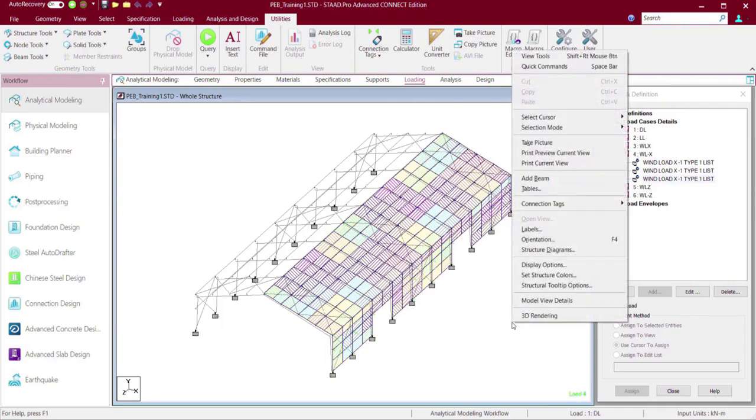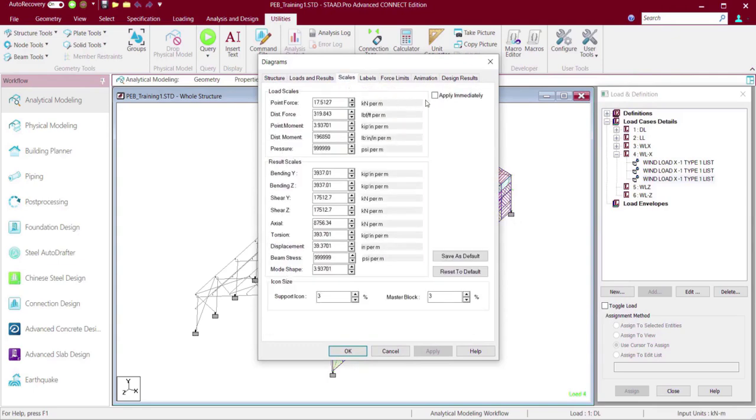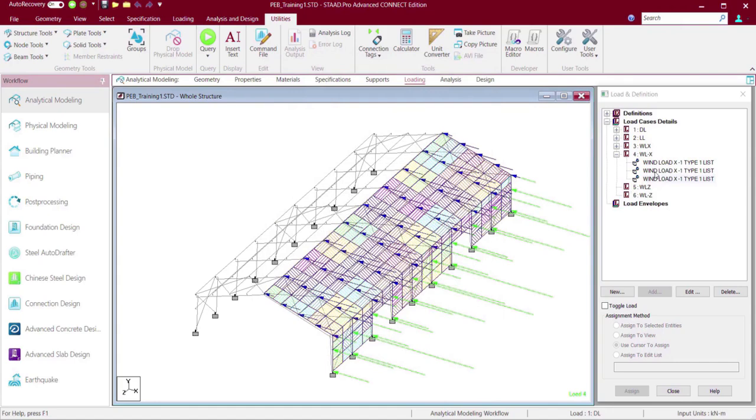Okay, so next we are going to apply the wind load in the orthogonal direction, that is, the z direction. Before that, let's see how the wind load vectors look. These are basically the nodal loads. You can see, as I mentioned, just scale it up. You can see these are applied on the different nodes, but the calculation is based on the panel that we have considered. So if the panel identification is not proper due to those bracings, then all those calculations would be jeopardized.